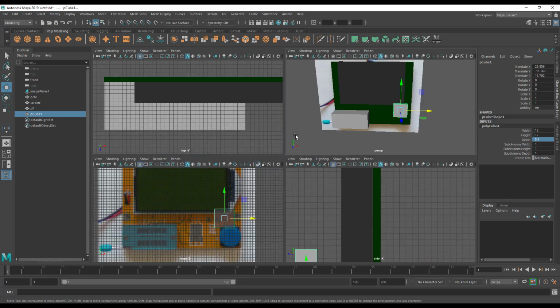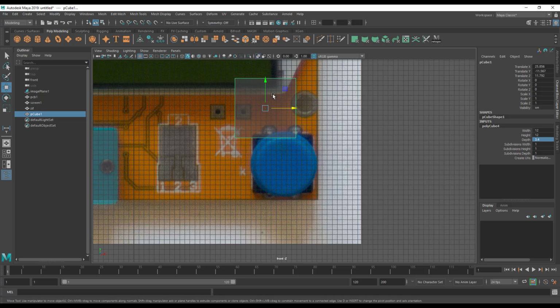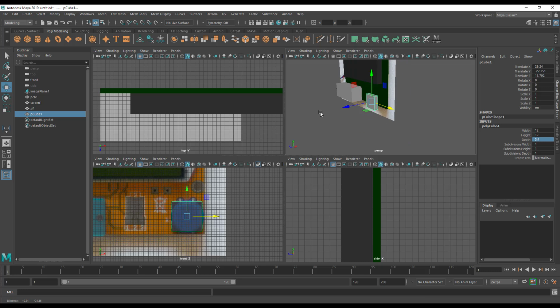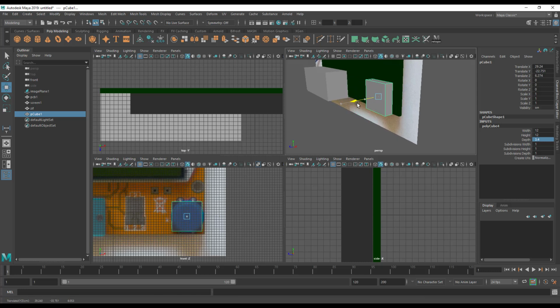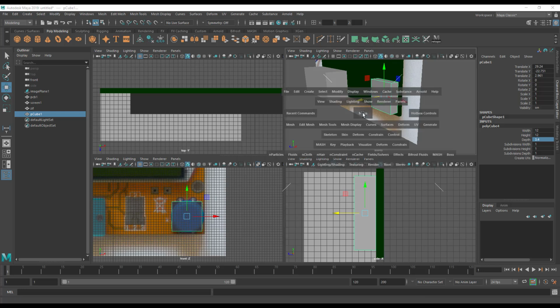Now, this is where the reason we have a really accurate reference, or as accurate as we can make it, is simple. Because I can't get in here, this little gap, and measure it with a digital caliper. But because I know my reference is good, I can simply use the reference to do it for me. Now that's never probably going to be quite as accurate as having a proper measurement of it.